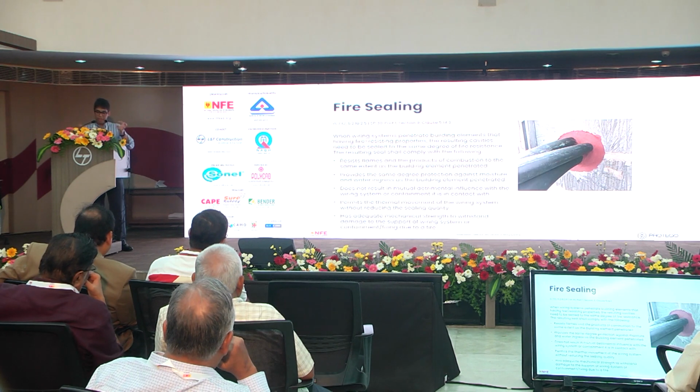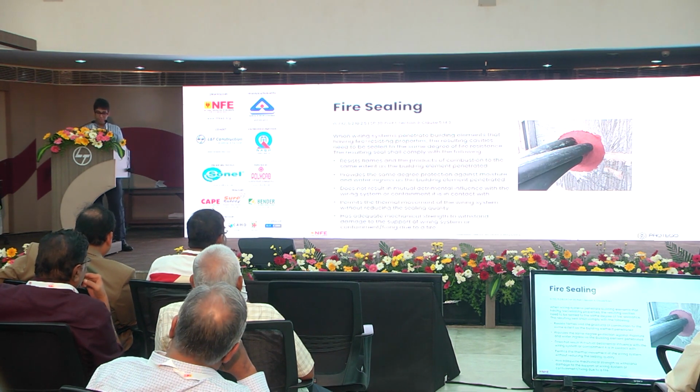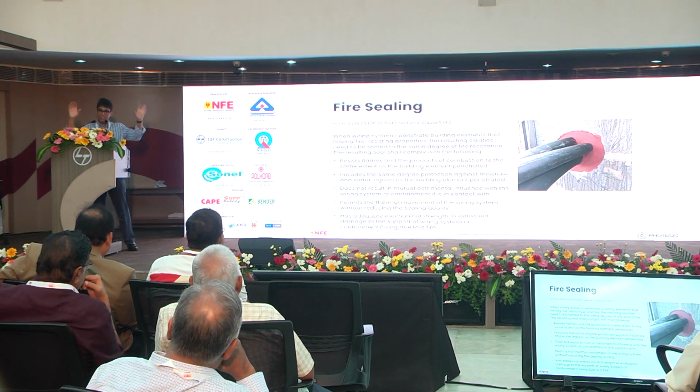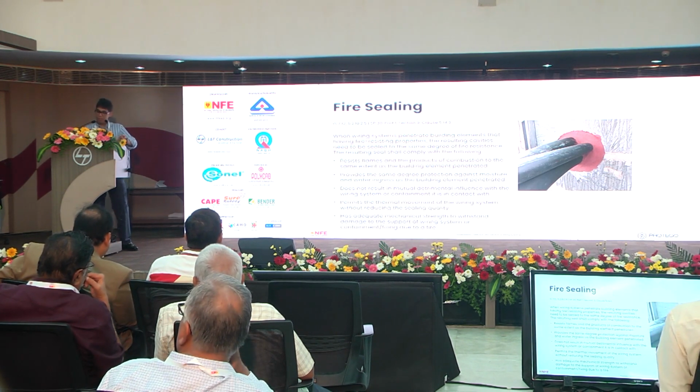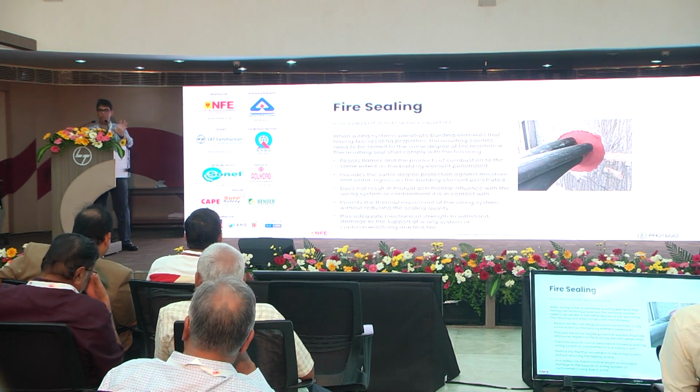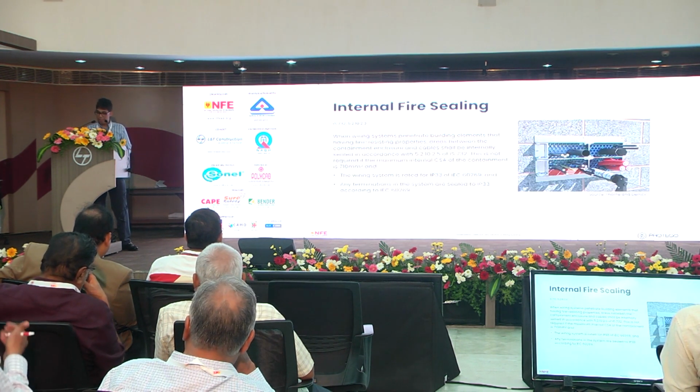And it also needs to allow thermal movement. When the cables get hot, they expand. When they're cold, they contract. And the mechanical damage due to a fire will also affect the fixings. So if the fixings collapse or the fixings are weakened, the fire sealant should not break simply because of the weight of the cables coming there. Obviously not forever, for a rated time.